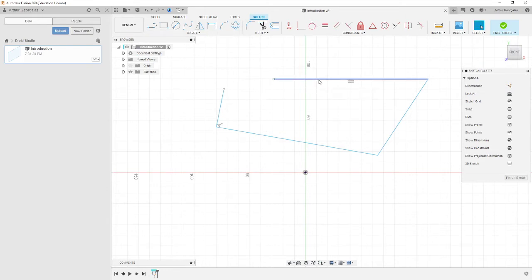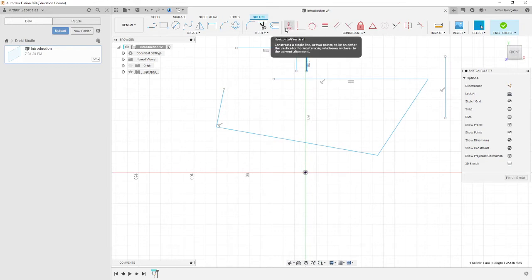One of the things I have noticed with Fusion a lot is if you're drawing something horizontal and then come in vertical, what it does is it adds a perpendicular relationship instead of just making, like even here, it's made this line perpendicular to this line over here, when in reality what we really want is just a vertical line. So much like SolidWorks, these little icons tell us what our relations are. So we can delete that, click it, and horizontal and vertical are one relation now.